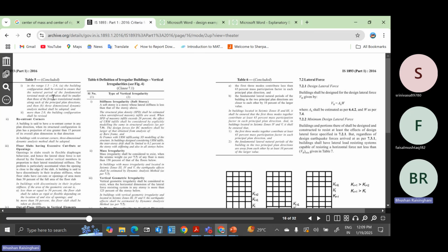However, in the ASCE 7 code, they have used a multiplication factor for this type of arrangement. So it is now up to the structural engineer to regulate the stiffness of the building and ensure that the time period is such that torsion is not governing, and delta max upon delta minimum can be 1.5 to 2. Though delta max upon delta minimum is more than 1.5, limited up to 2, the time period is regulated so that torsion is the third mode, not the first or second mode, right? So this is a very critical point.